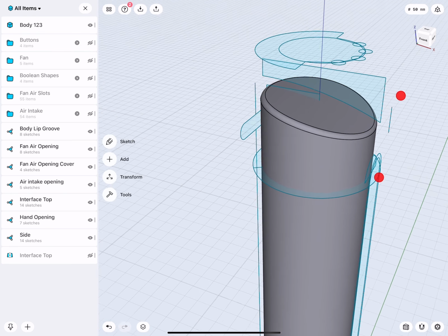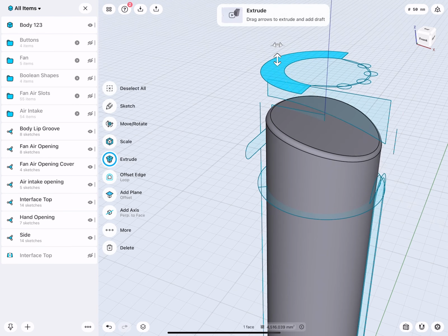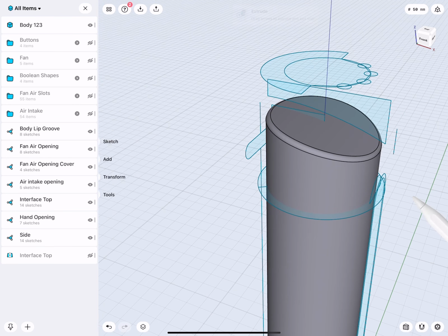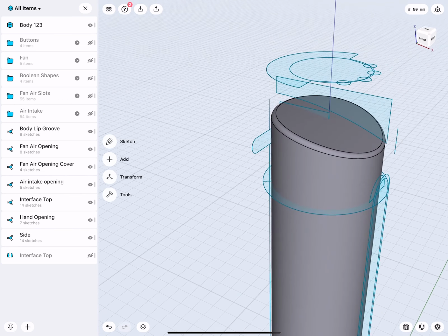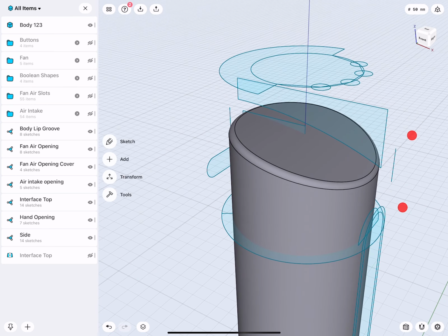This will be created by this shape. And then also the top part needs to be removed. And then I need also to shell and create lip and groove and all this stuff. And the trick here really is understanding in what sequence I have to model everything. So far that was very easy. Now we need a cylinder and then we can trim it, we can round it.